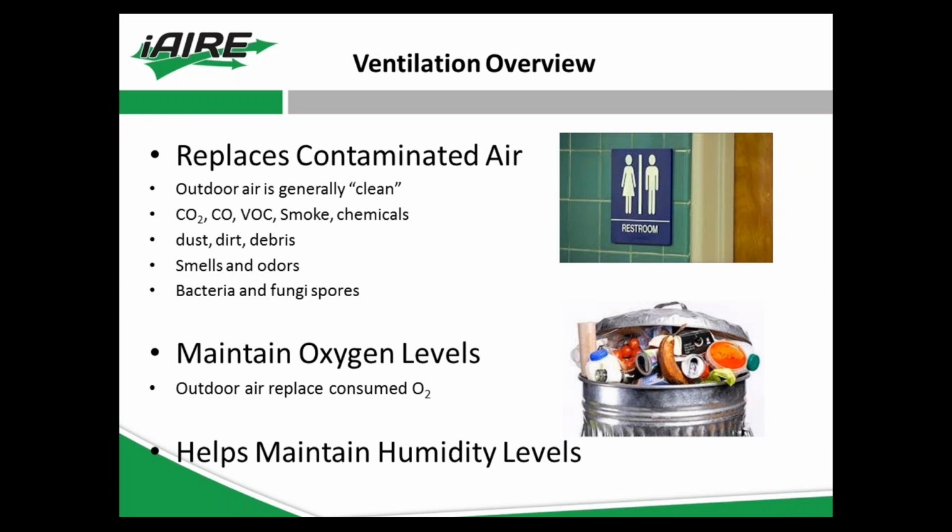Ventilation is basically necessary to replace contaminated air, which I'm sure you're familiar with. Generally, we do that by introducing outdoor air, which is considered clean air. That may not always be the case. Those of you from the downtown area know that you may not want to be taking in outside air right off the street side.